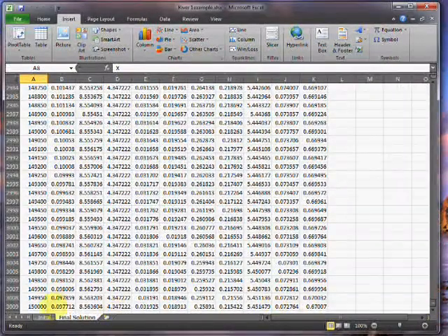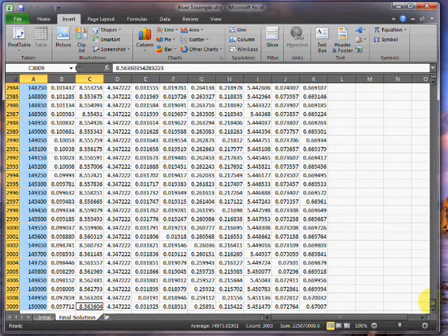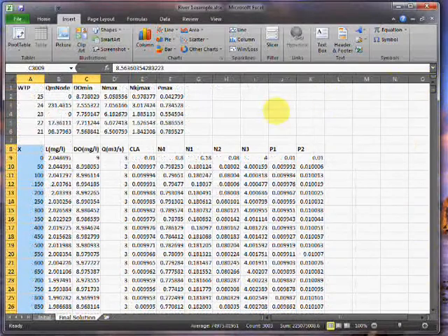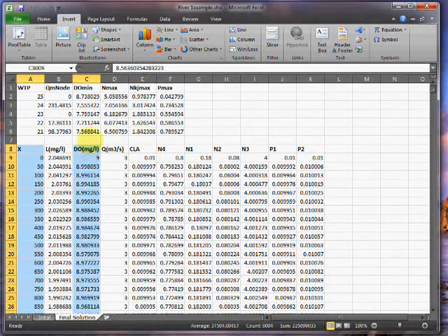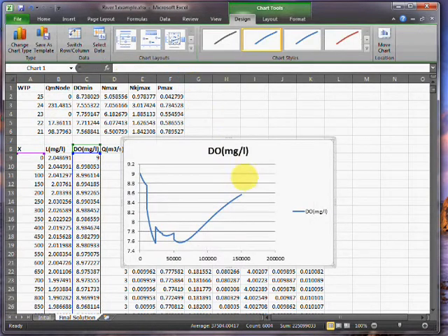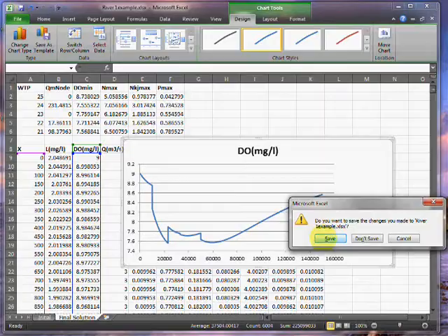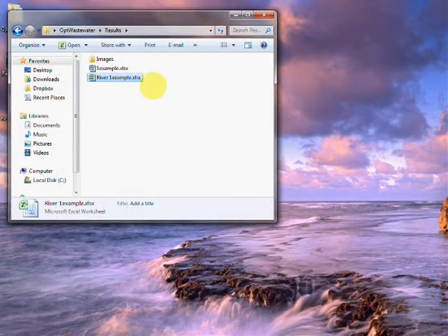Let's take a look at the dissolved oxygen sag curve concentration for the solution of the problem. As expected, the dissolved oxygen concentration is always larger than the constraint of 7.5 milligrams per liter. The concentration curve decreases with the wastewater discharges and then recovers along the river. Also, it is perceptible the improvement in the concentration resulting from the flow increment given by the tributary stream.